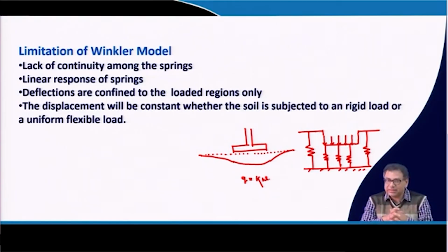But that can be achieved, but in the normal case, if you consider a uniform K value along the length or width of the foundation, then whether it is a flexible foundation or a rigid foundation, your deformation will be constant or uniform. So, that is another limitation. So, now we have to remove all these limitations.